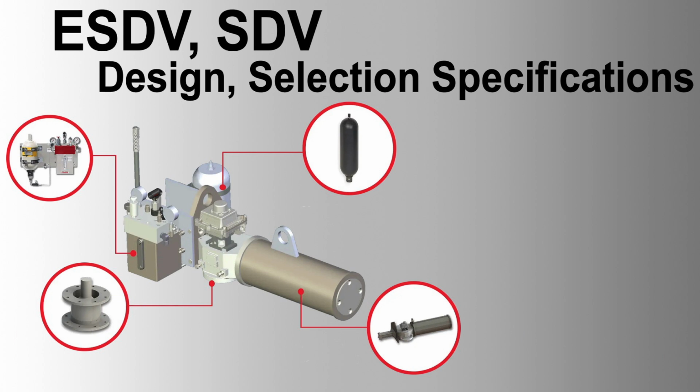Materials, material selection. All materials shall be new and free of defects. Valve materials should be selected to minimize corrosion from process and environmental conditions. Compliance. All process-wetted materials must comply with NACE STD MR0175. External components. Materials exposed to the environment must be non-corroding to meet site design and data conditions. Prohibited materials. Cadmium plating or galvanizing is not allowed. Bolting must adhere to the applicable data sheets.